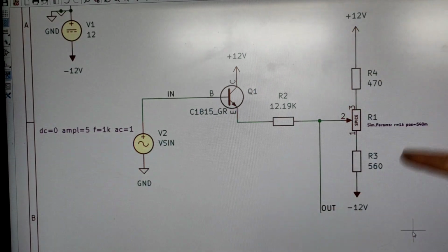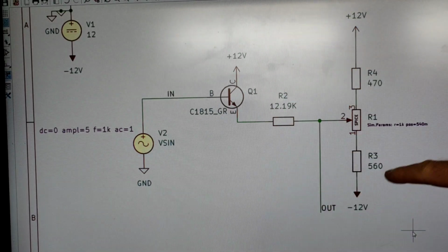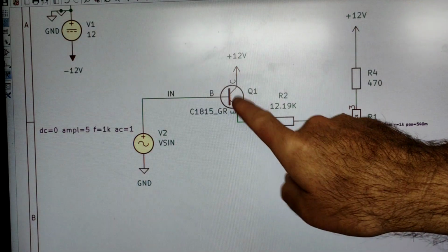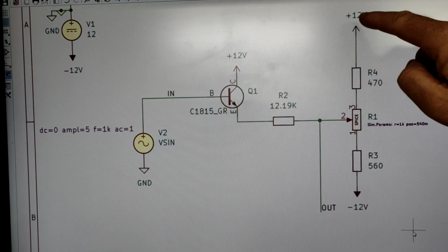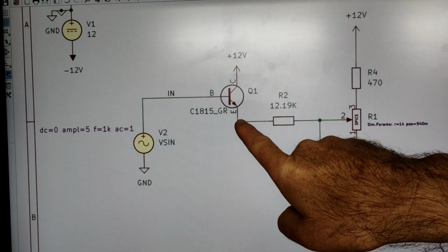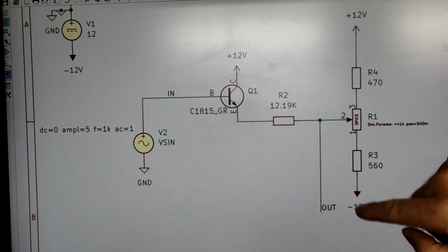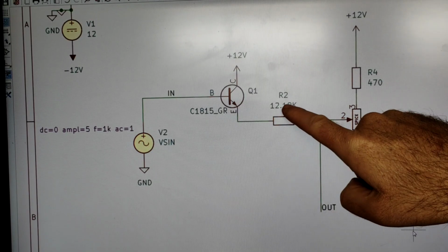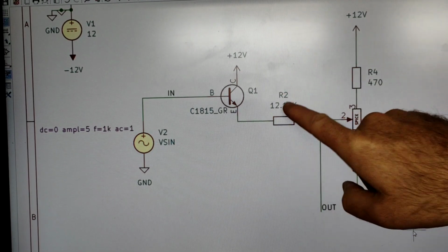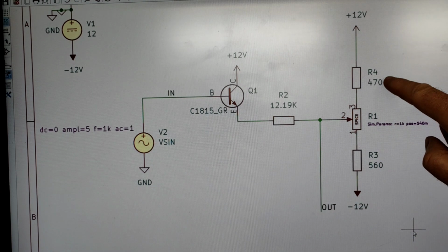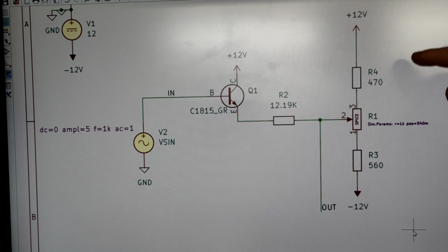And the easiest way to think about a network of resistors like this is that the voltage here is going to be a weighted average of what it is at these 3 points. And the weights on that average are the reciprocals of the resistances, which is also called the conductance.